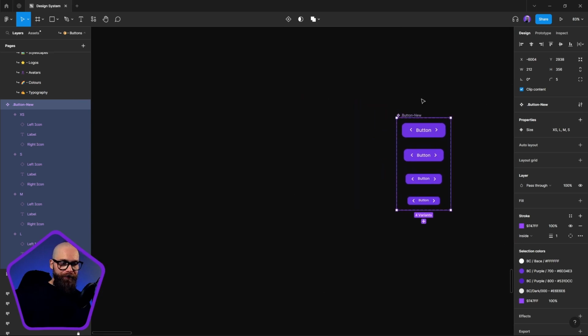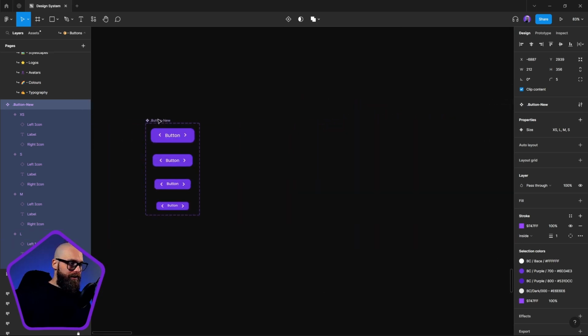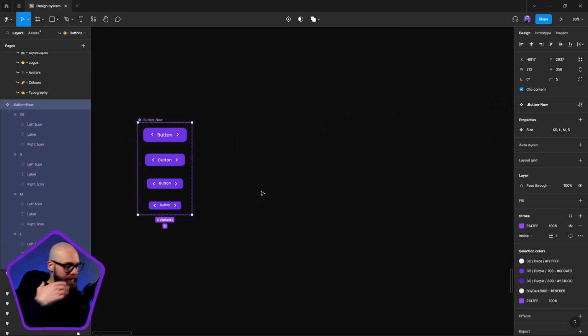So here we go. First layered component off to the side. Now, I need to understand that every time I add a actual layered component level, if I layer too many components, the way that they propagate the information up the chain starts to break away. I find that usually 2 layers up is fine.